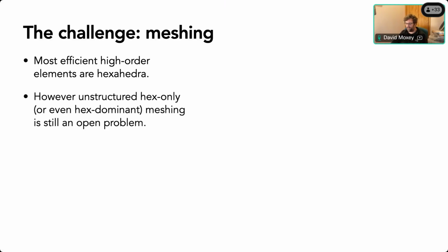The problem is that if one is interested in these more complicated geometries, unstructured hex only, or dare I say even hex dominant meshing is really still quite an open problem. It's not to say it's impossible, but it takes a lot of time and effort to create one of these hex only or hex dominant meshes.